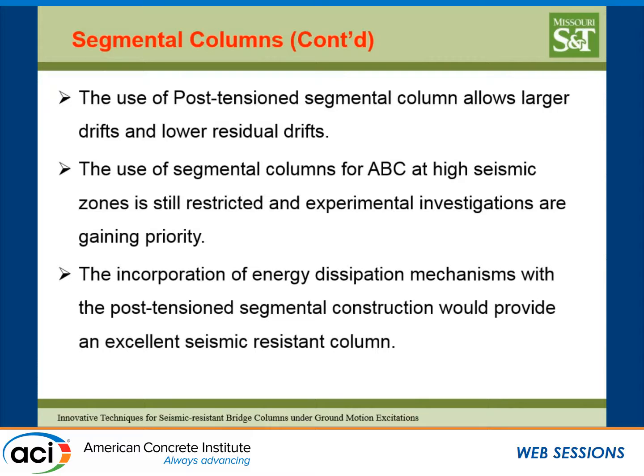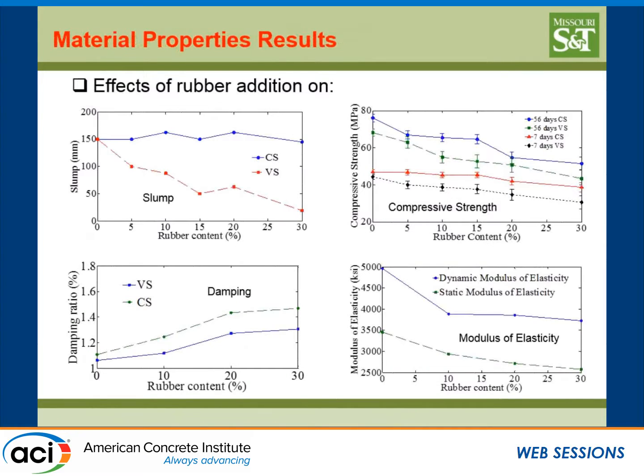And as you have seen also in the first presentation, with most of the rocking system, you need some energy dissipators to combine the post tension. Otherwise, you would get a very limited energy dissipation, which makes you have a higher demand in displacement in your columns. These are the two systems that we propose, the internal and external.